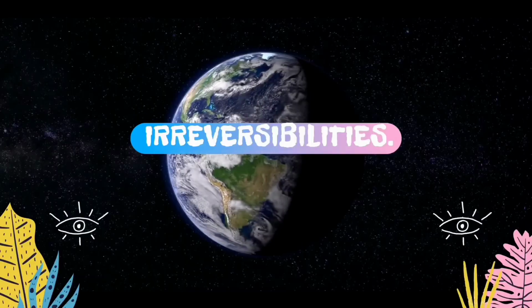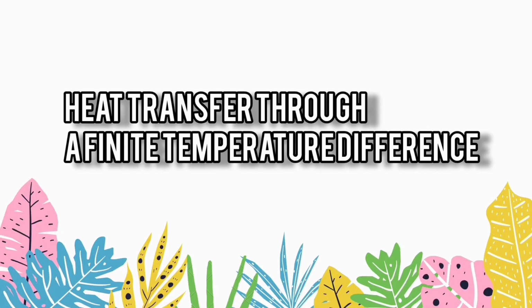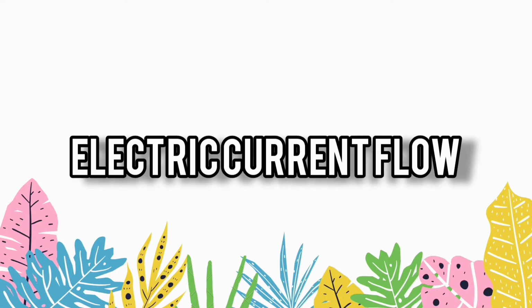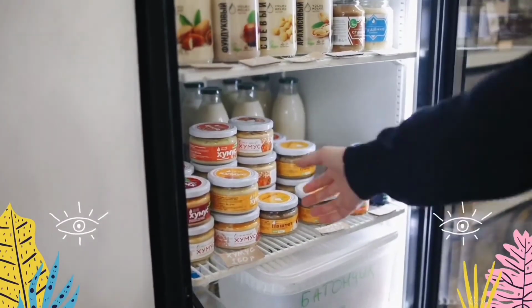This is because of irreversible factors. The factors that cause a process to be irreversible are called irreversibilities. They include heat transfer across a finite temperature difference, unrestrained expansion of a gas, mixing of two gases, friction, electric current flow through a resistor, inelastic deformation, and chemical reaction. The process is irreversible if any of these effects are present.